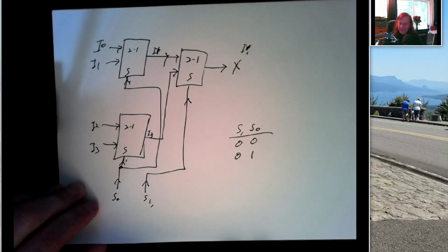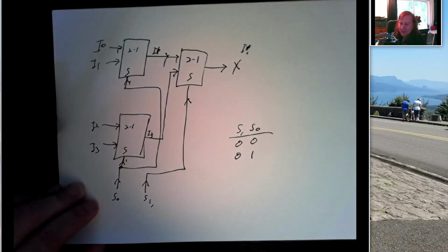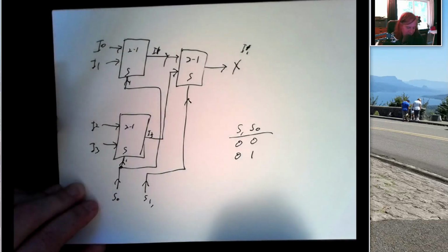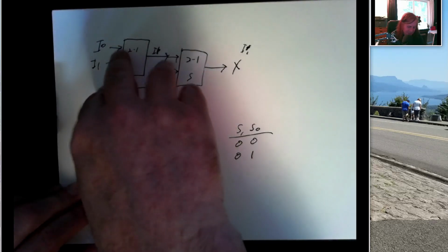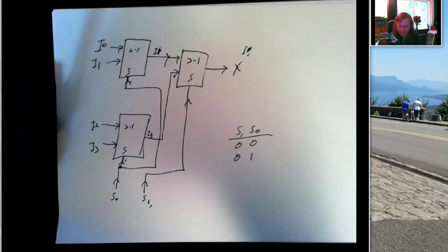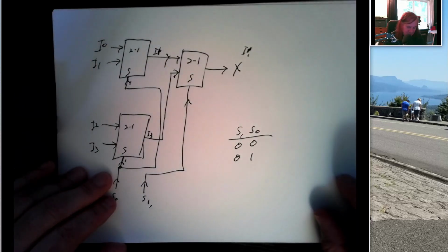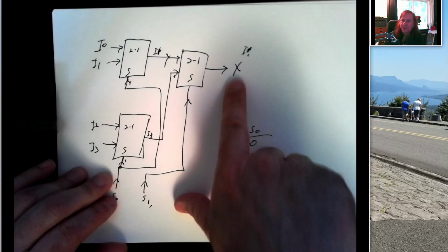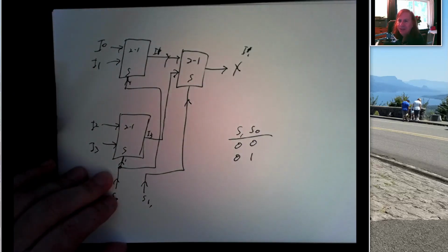And if we wanted to make an 8-to-1 multiplexer, we could use a couple of 4-to-1s and a 2-to-1 and build it up like that. So we can make these mux trees, right, that select your inputs and filter them down to smaller and smaller sets of possible inputs, and eventually generates one output, which is your desired input. So muxes are great building blocks.